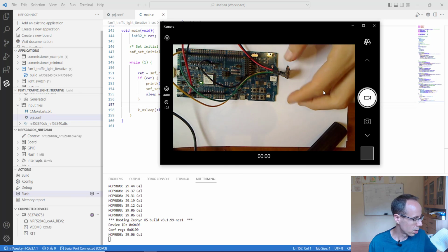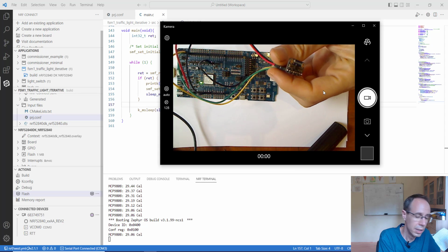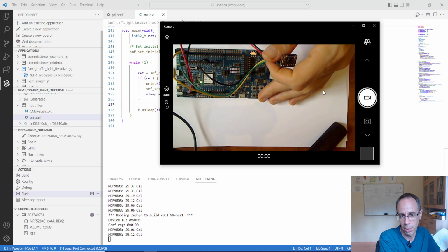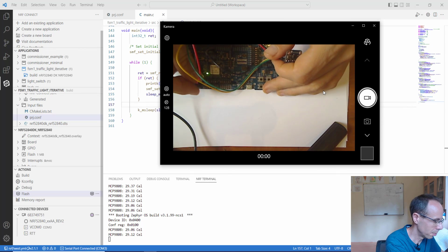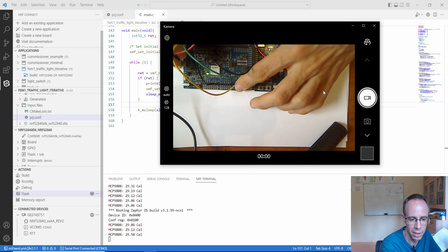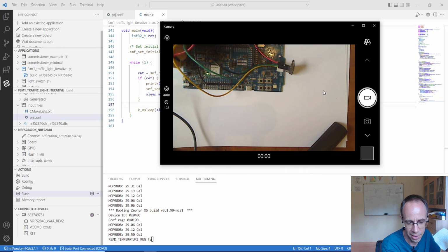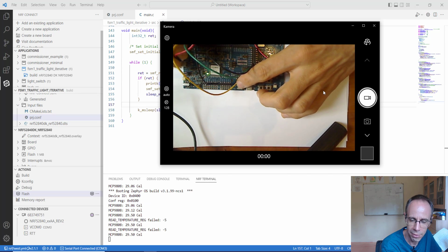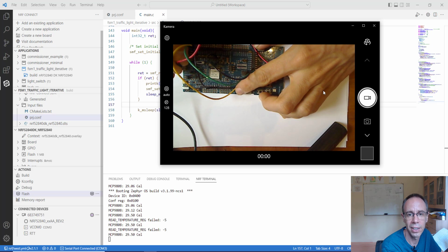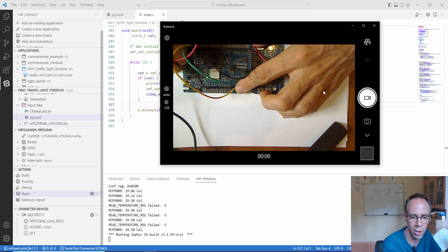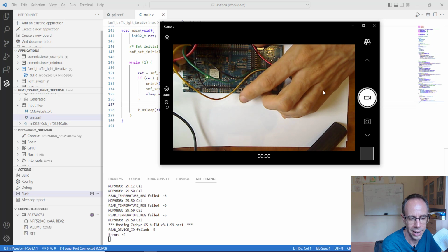You're seeing it's working when I have our sensor here. The problem is when we're having a device tree and the sensor is not plugged in at the beginning. So I put the power out, for example, I reset this board. You see when I don't reset it, I will get an error and it's still trying to read out the next time. But when it's not plugged in at the beginning, then normally we get an error with the driver and we cannot connect to the sensor anymore. Here I get an error.